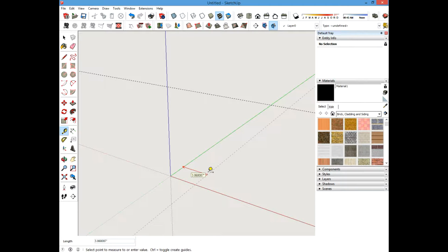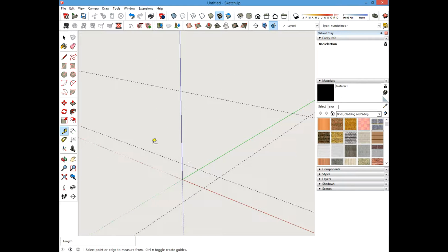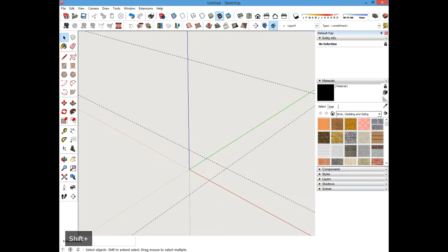If you know a little bit about wood, then you'll know that, for example, a 4x4 is not actually 4 inches by 4 inches. It's actually closer to 3.5 by 3.5 inches. So I'm going to think of this as using a 4x4 for the legs. However, I'm going to set it at 3.5 by 3.5, and it's really important when you're designing to try to get as close as you can to the real measurements of the material that you're going to be using. So let me double check that. 3.5, 3.5. Okay, so let's put a rectangle down.